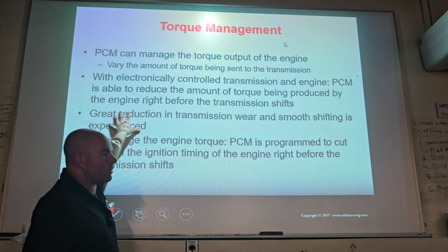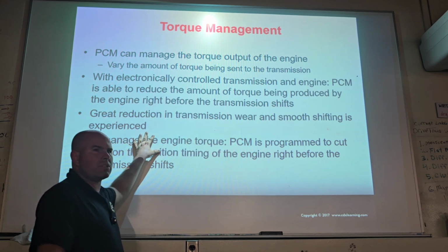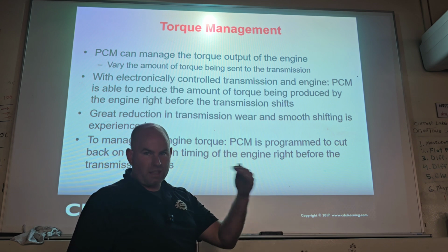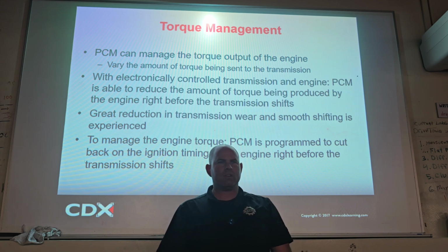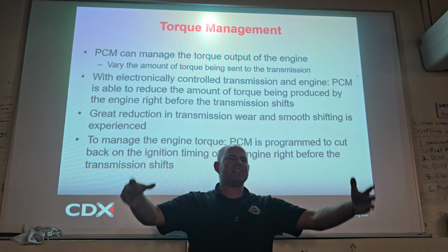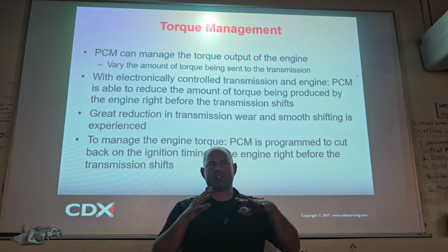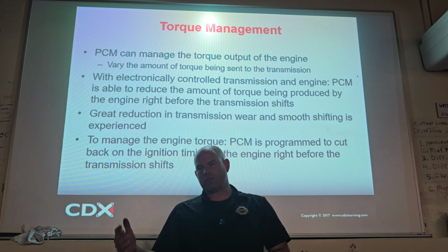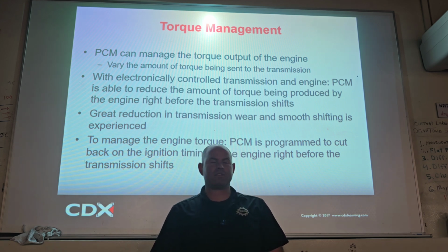And then torque management, we talked about a little bit too. If they know your 1-2 shift being really hard is going to damage some things, the torque management program can actually chill that out a little bit to protect itself, to make it last longer. Now, if you take it to the tuner and you tell the tuner you want the car to be as fast as possible, what do you think the tuner is going to do? Erase all this torque management. Clear that all out of there. Give it full power. Now, what would that do to your warranty? Obviously, that would be voided. And you can see why. They know that transmission might not take that full 1-2 shift at 100% power, so they torque manage it. The tuner goes in and says, nah, just give it the beans, as they say. Okay, if it breaks, that ain't covered.